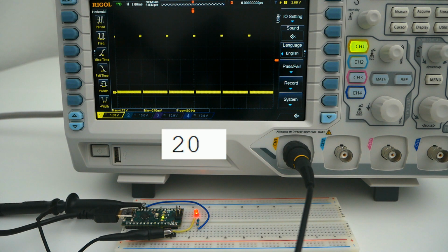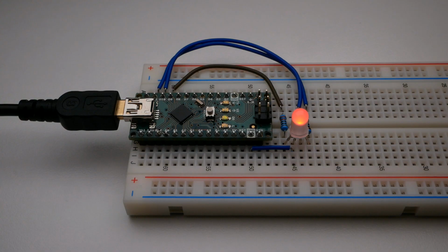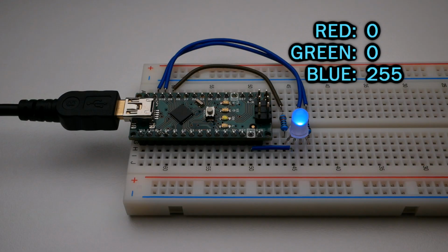This analog write is very useful when using RGB LEDs, which can create a wide range of colors using a combination of 3 color LEDs in one package. The RGB LED has red, green, and blue LEDs inside that, depending on the brightness of each one, can produce different colors. In this example, we can connect an RGB LED connected to pin 9, 10, and 11, so we can experiment changing the brightness on each color to see the effects on the entire LED. If all 3 colors are fully on, it produces white light.